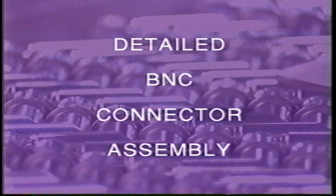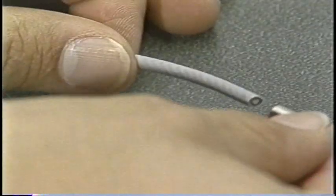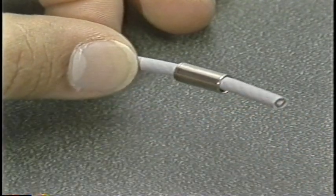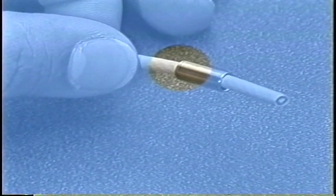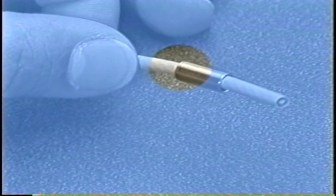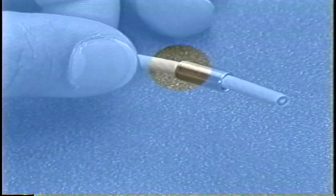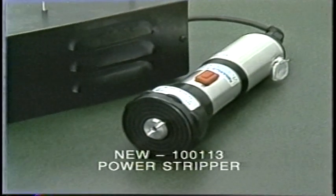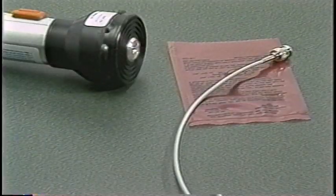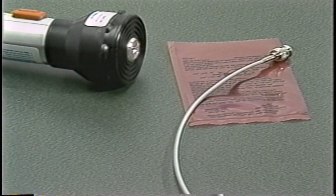The detailed sequence of assembly is as follows. Slide the outer crimp sleeve on the end of the cable. The step at the end of the sleeve must be facing away from the connector body. The cable must be stripped to the proper length. The NEW 100113 power stripper may be used with the correct cutting head for the cabling being used. This demonstration will be done with the power stripper and 735 cable.